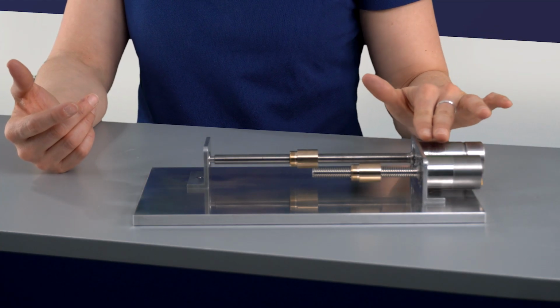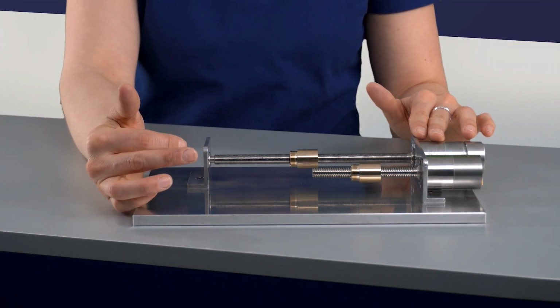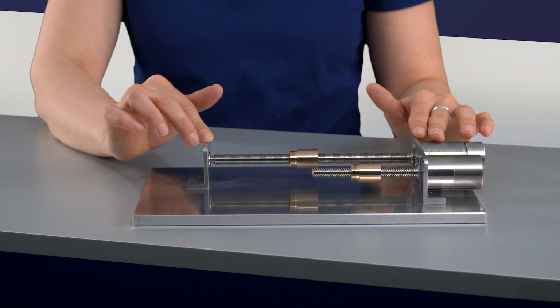For the next two lines, it is relevant to understand the support method in your application. We consider the two most used in our datasheets. In your adapter we have a radial and an axial bearing, creating a fixed bearing. Therefore the support method depends on the fixing of the second side. This is the fixed single support.